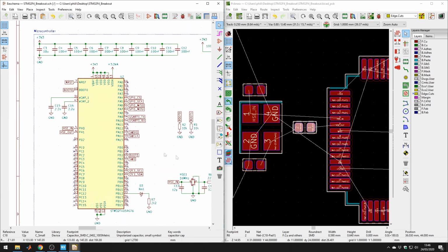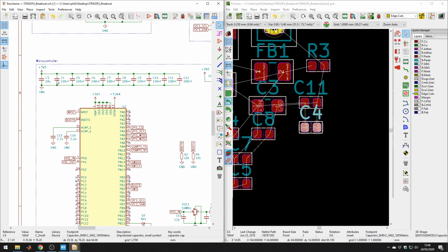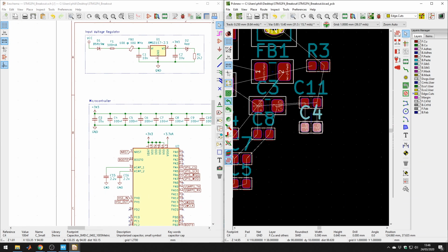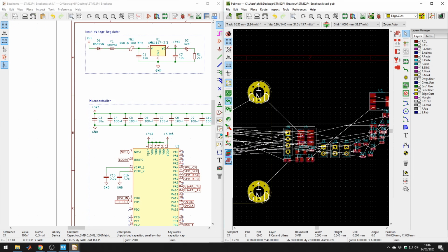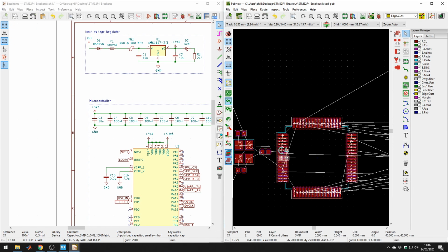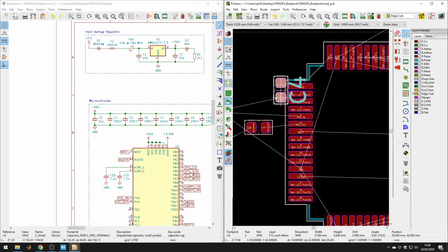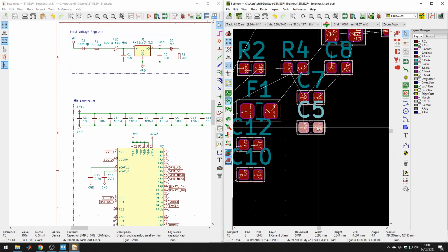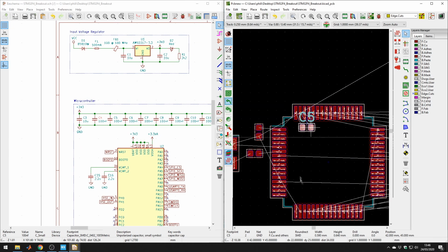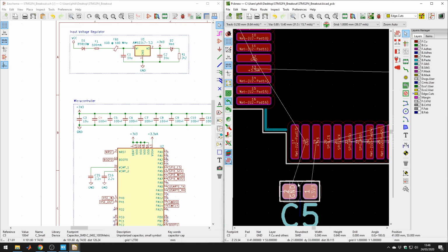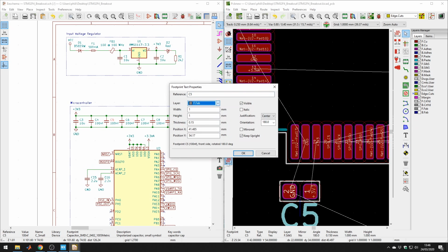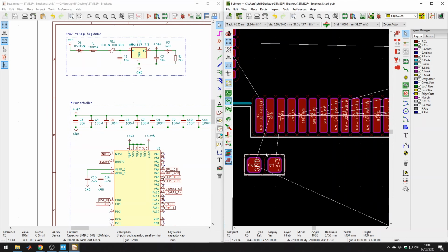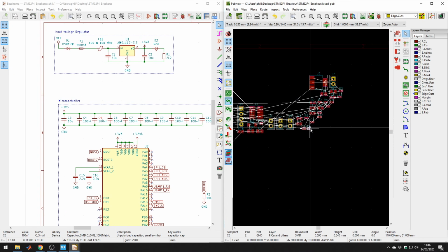Now, what about the decoupling? So let's start with the smaller ones first. It's 100 nanofarads. Remember the bulk 10 microfarad is close to the MCU but not very close to the pins. So pin 1 is here, and that's the VBAT pin, and that only gets 100 nanofarad capacitor. Then we want pin 19, should be somewhere down here. You'll see the 3.3 volt and the ground pins are very close together, and exactly for that reason, so you can put the capacitor essentially right in the center, line it right at the center of those two pins. Remember, we want 2 of these here.